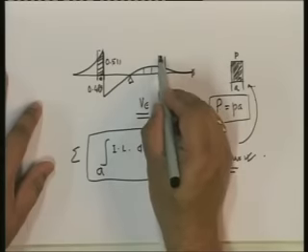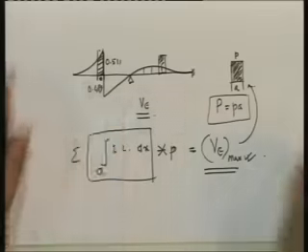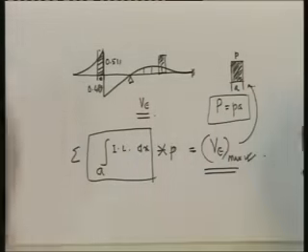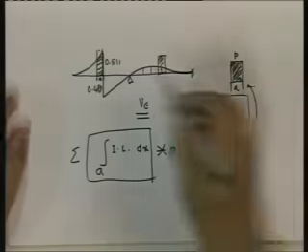Once you place one load at the maximum, the others come automatically, because the distances between the wheels, axles and loads are fixed. So you can always find it out, and this way you find out VE max. Of course, I'm illustrating it with VE max.